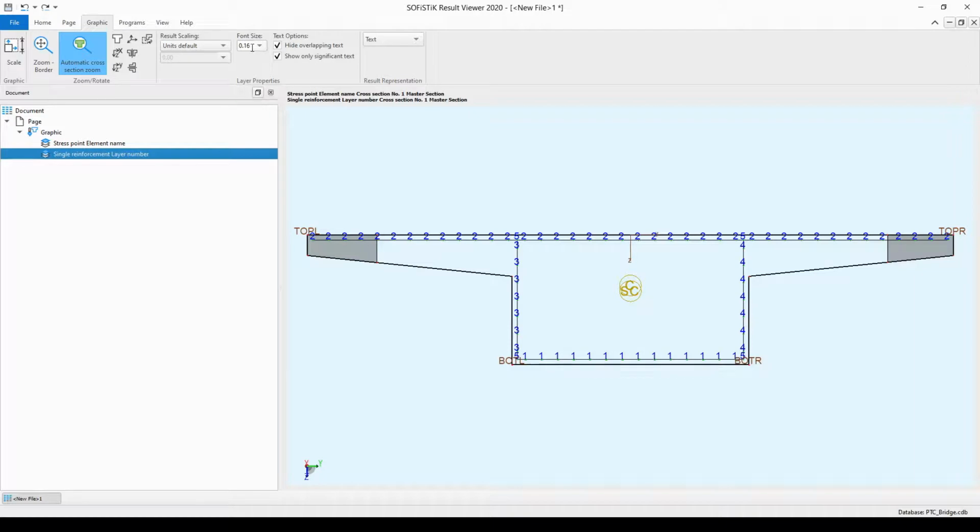For example, if I want to change the size of the reinforcement text, then I will simply highlight the text size, and I will change it from 0.16 to 0.12 and then hit enter, and then really you can see in the layer the representation of the text has changed. And I believe now this graphic shows a more reasonable representation.